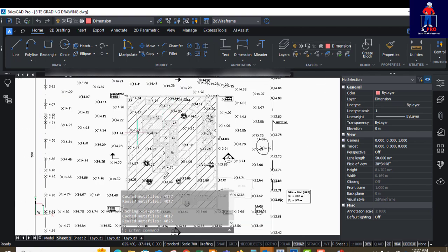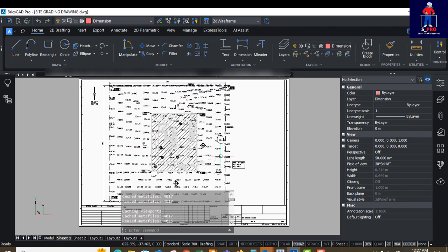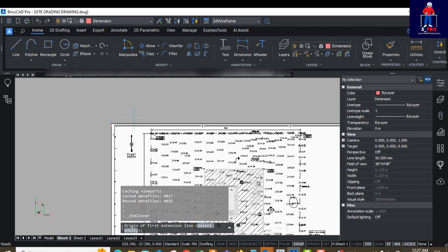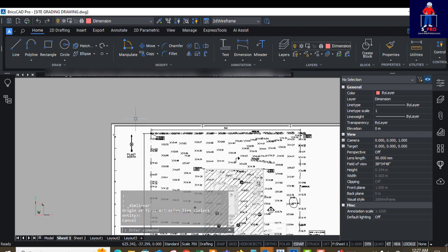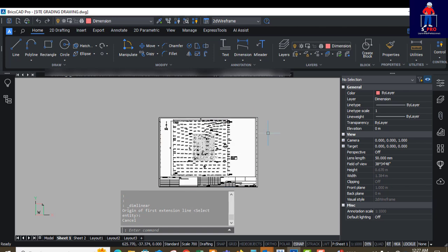To get this particular lesson, I have to make a drawing very faint. So I'm going to explain all this. Like I said before, I like keeping my drawings in paper space, where the paper will be the actual paper size. What this paper here is, if it is A3, is actually A3. If you dimension it, you are going to get 450 by 297.